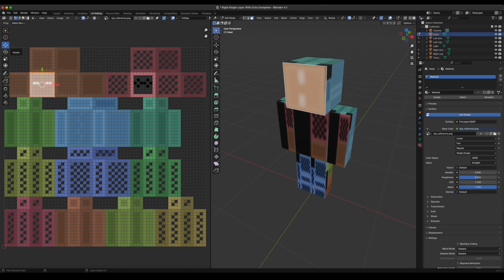The other, simpler method, which we'll use for this tutorial, is to rotate the UV island and make any fine adjustments from there. To do this, we select the entire island, press R, and then type in 270, then enter. We can see that this immediately corrects the orientation of the mapping to the model's face.